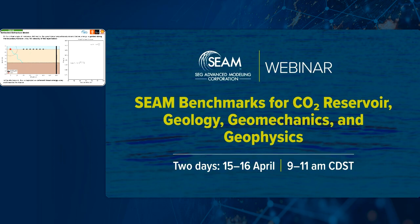Here I demonstrate the path of a reflected refraction against a subvertical boundary. The critical incidence angle, or this angle here, is defined by the geophysical properties of the two layers. The energy travels along the boundary at the velocity of the layer below. Within the shot-gather domain, this appears as coherent linear energy and can be defined by adaptations to the refraction move-out equation by adding 2d minus x, d being the distance to the vertical reflector.